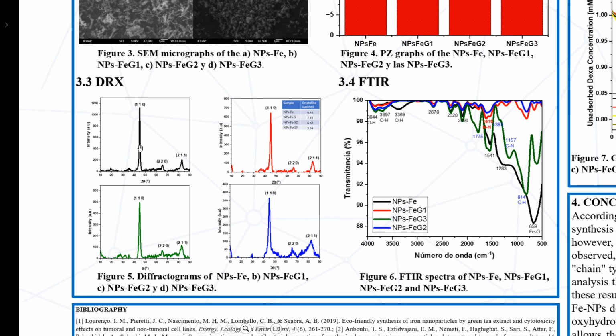However, the less intense peaks correspond to the 220 and 211 planes, which are reduced by the presence of glycine. From these results, it's confirmed that the layer of oxides and hydroxides mentioned previously is thin and is not present in significant amounts to modify the structure.